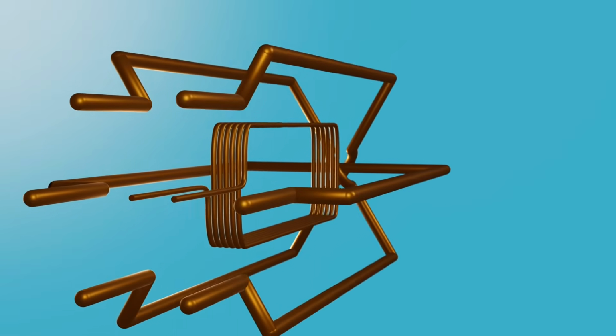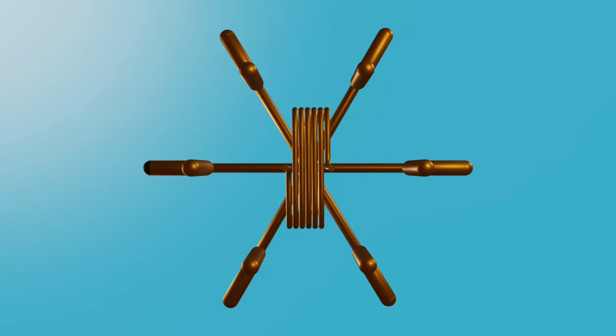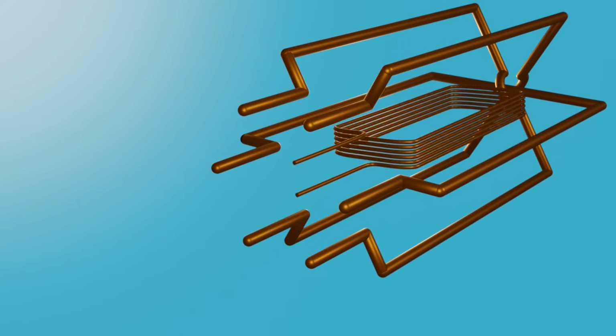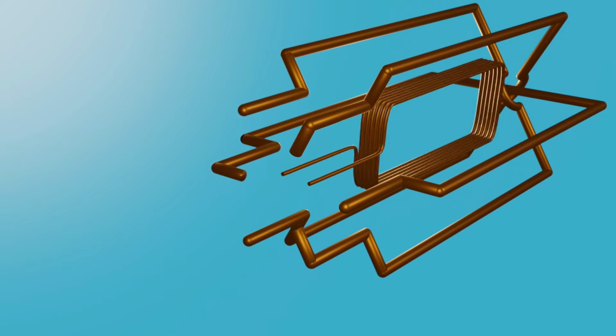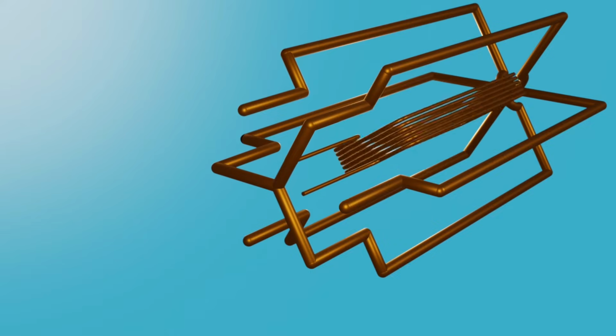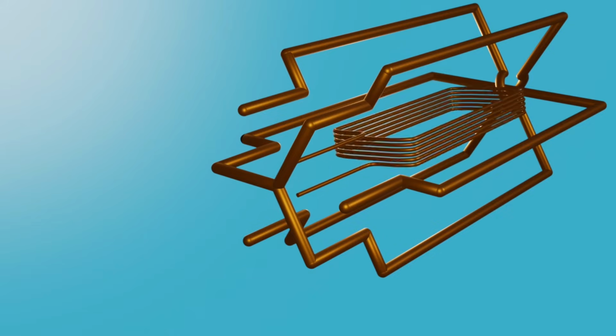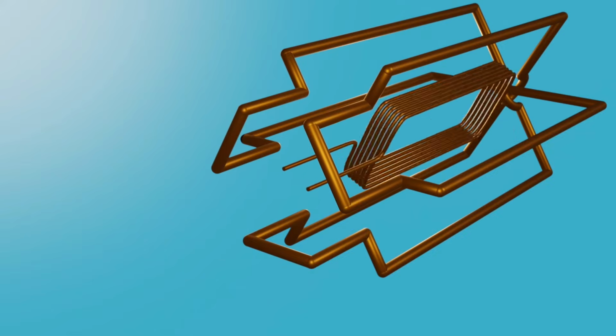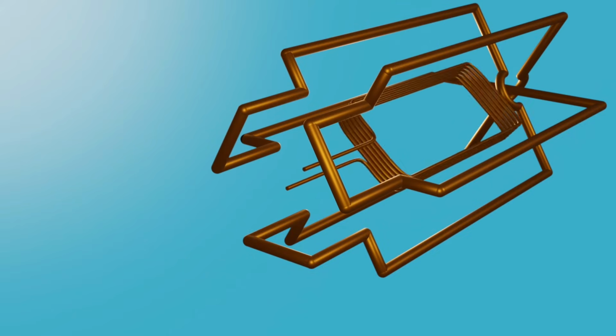The coils on the outside are again offset by 120 degrees and in reality will consist of several coils spread around the outside of the generator to maximise efficiency. But again, keeping it simple helps us to understand the principles involved. One end of each coil is connected to the ends of the other coils in one of two ways to give us either a star or a delta connection depending on the type of generator it is, and the other ends of the coils are connected to the outside world, giving us our three-phase supply.